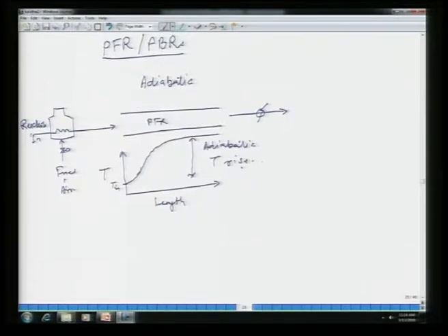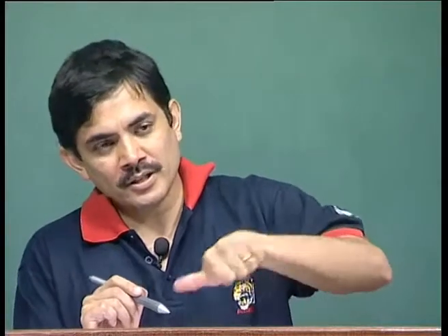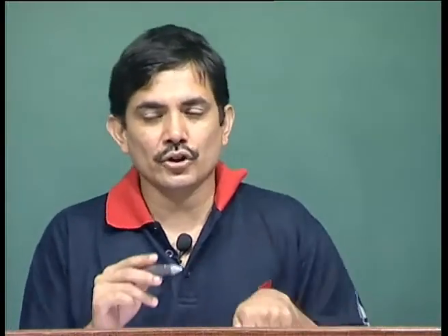You can also have a plug flow reactor which is a packed bed reactor, in the sense you have a catalyst loaded bed, and this is actually very typical. You actually have an adiabatic packed bed reactor. So, there is a catalyst bed. The hot reactants by themselves would not react, but when they come in touch with the catalyst, because the catalyst reduces the activation barrier, reaction takes off. The main reaction takes off, accompanied by side reactions as always.